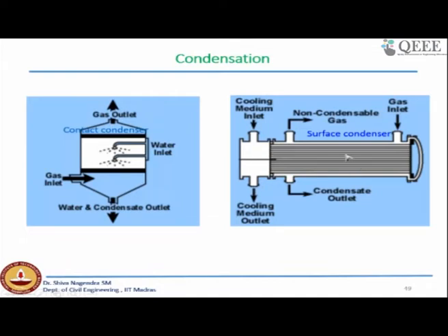You can also remove particulates and gaseous pollutants with condensation. For example, you have a known pollutant and you know its freezing temperature, so you can use that as an input to design the condensation mechanism. Then you can remove some of the pollutants coming in the gas stream.